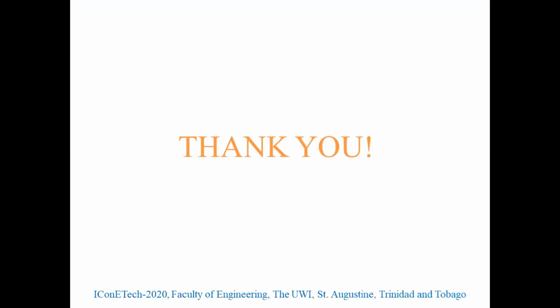Okay, so we have a question from Dr. Beichu. Will these fabric filters be more efficient in dealing with the high turbidity encountered during flooding in the wet season? Well, it should be. So far from my tests, it has proven that it is quite effective with the turbidity, the linen fabric in particular, and that is the aim of my research. So if it is more efficient, it will prevent the water treatment plants from shutting down by retaining more particles.